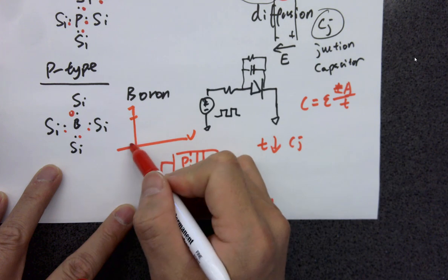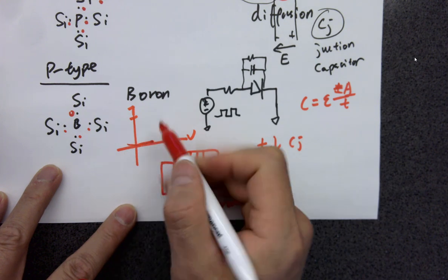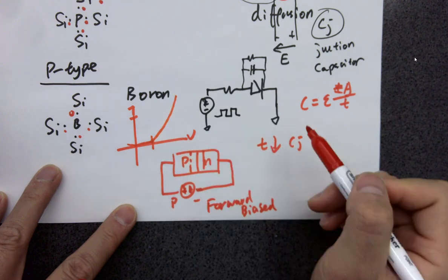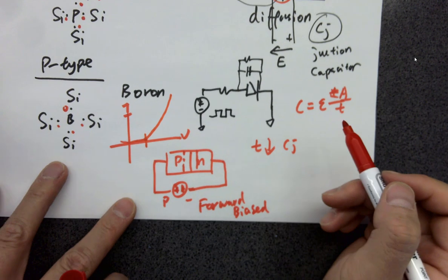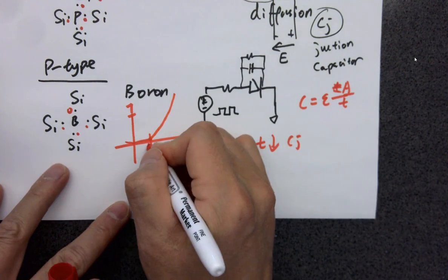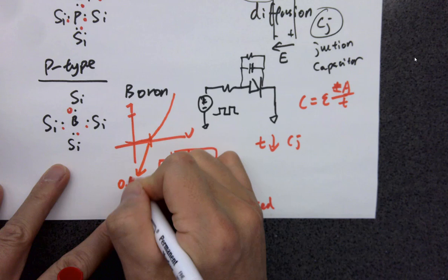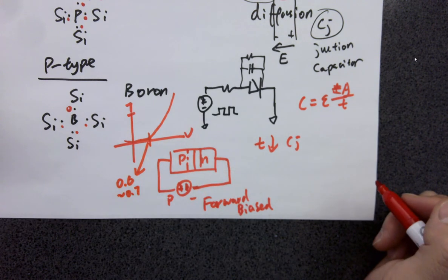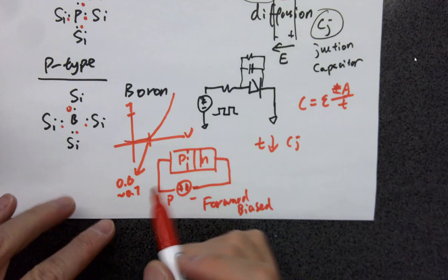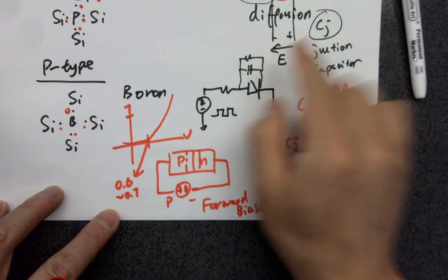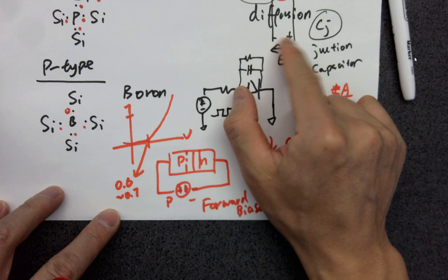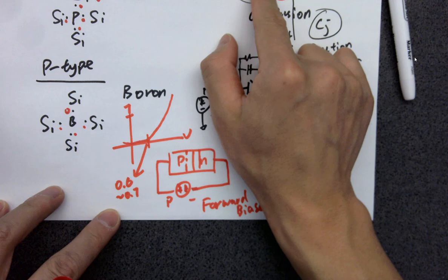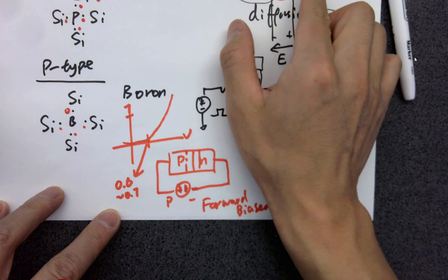Whenever the voltage passes a certain threshold voltage, the current starts going up. For silicon material, usually this is like 0.6 to 0.7 volts, right? That is the built-in potential formed by this electric field. So you have to overcome it in order to pass current through that diode.